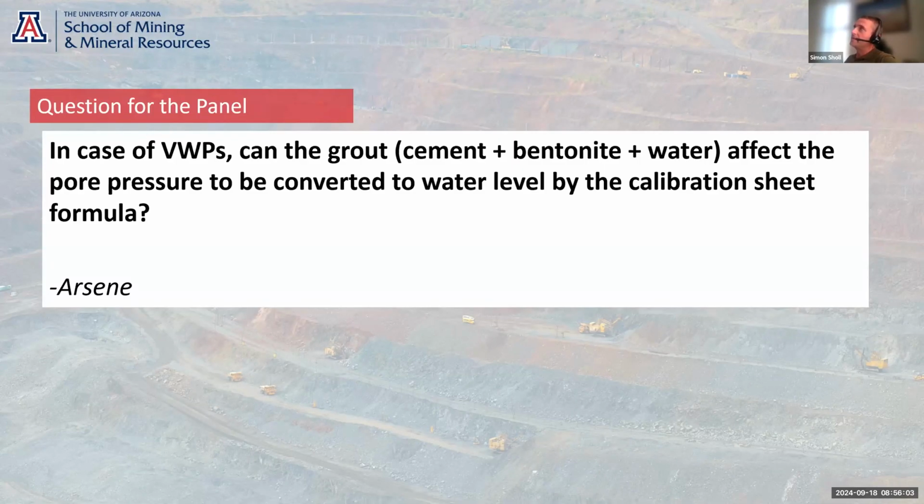If your grout mix is higher hydraulic conductivity than the formation it is in contact with, water will obviously preferentially move through your grout rather than the formation. So that will have an impact, but it's generally very rare, as long as you use a standard mix, and unless you're in an incredibly low hydraulic conductivity environment, it's typically very rare. So broadly, I would say no, the grout mix doesn't have an impact.